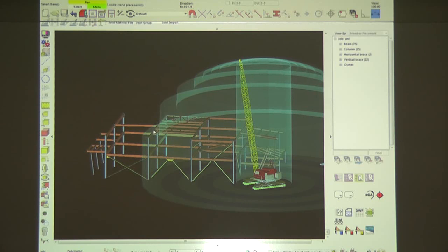Well, the difference between the top of this ring and the top of this ring is a chart inside of the crane saying, I can only lift 5,000 pounds at this height, but I can lift 6,000 pounds at this height, and so on. The closer it gets to the crane, the more it can lift. And that's all calculated in much the same way as the design calculations you've seen for the connection. We have similar calculations for the crane. What can it do at this location?